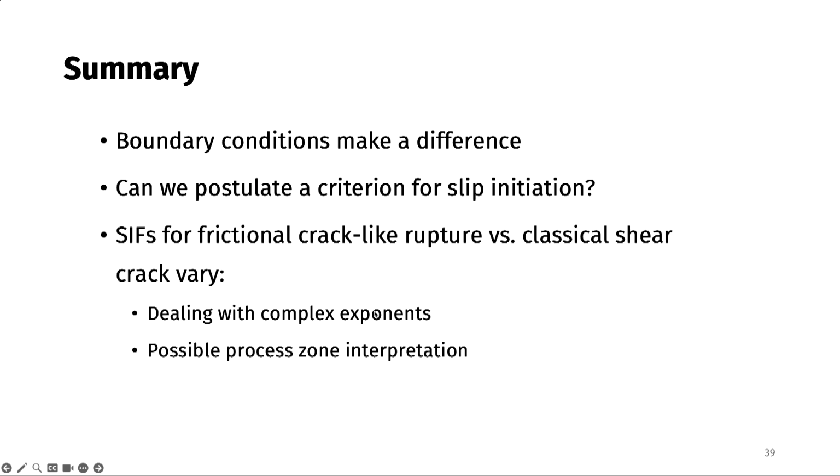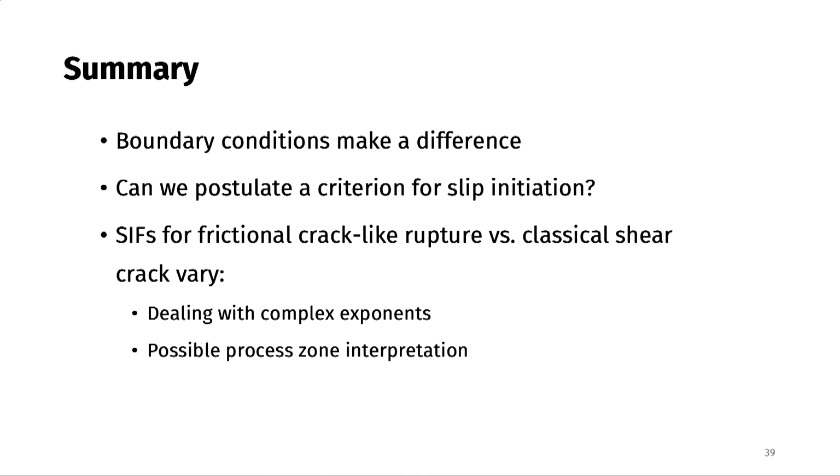The stress intensity factors, there is a technical problem. Again, I don't want to get into these details, but for interface cracks, if you worked out details for moving interface shear cracks, you will often see that the stress intensity factor has a complex exponent, right? And that is problematic because it gives something called an oscillatory stress ahead of the crack tip, which is unphysical because it leads to things penetrating and so on. That comes up in our theoretical model as well. We think that the numerics, the lattice model, doesn't have that artifact.